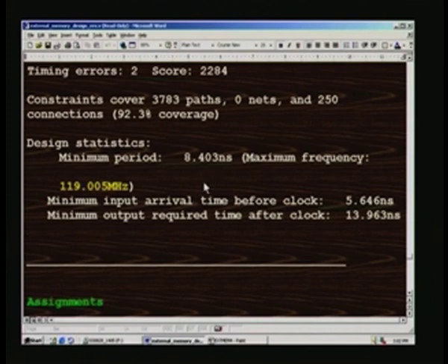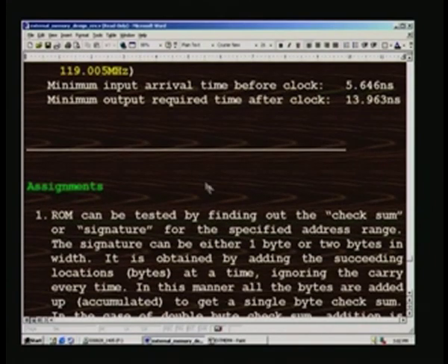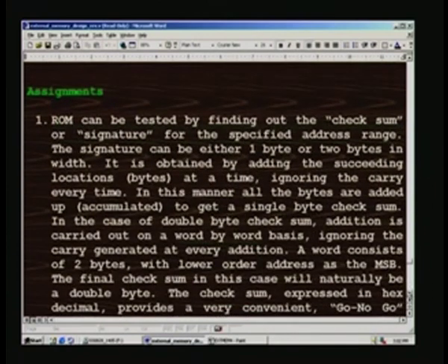So, we are justified in running at 100 megahertz, that is the clock rate is 100 megahertz, whereas the access is 50 megahertz. So, with 50 megahertz we can have actual RAM. This has been designed with the vendor's device as such taken into account. So, that means to say that it is a standard RAM available, so that we may use later on in the actual project, that is 64K into 24 bits.